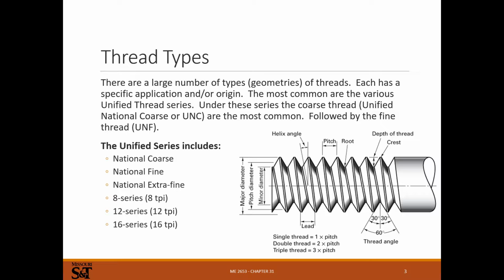So that's the difference between multiple starts, multiple leads. Again, probably just confused everybody, but the main thing is a single thread is just one continuous helix that wraps around that gets all of these points. In a double start or a double lead, there are 2 separate helixes that are offset from each other, and something that starts in one of those helixes never gets to the other one. Essentially, the helix angle would be twice as steep for each helix, and you have these 2 helixes that are nested within each other.